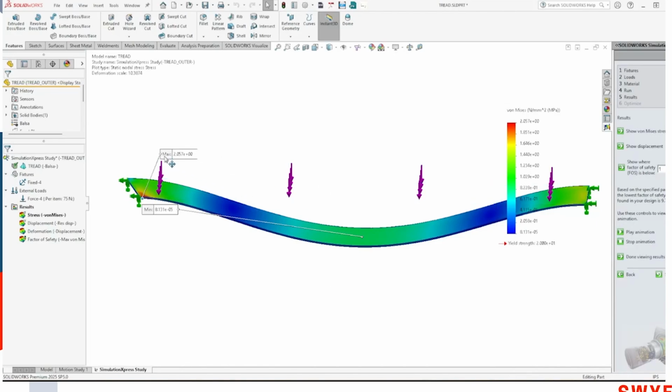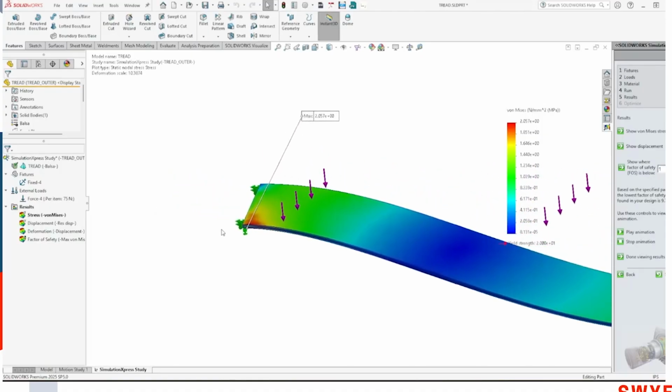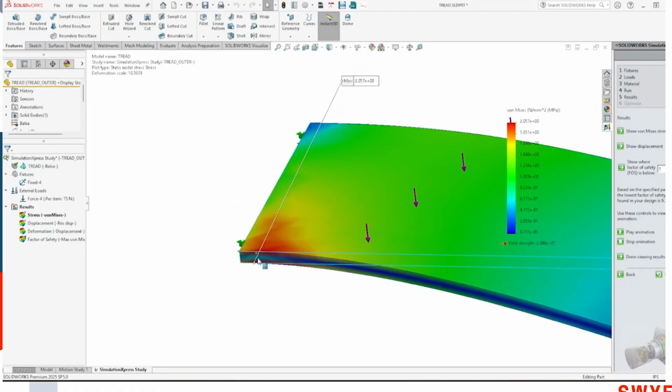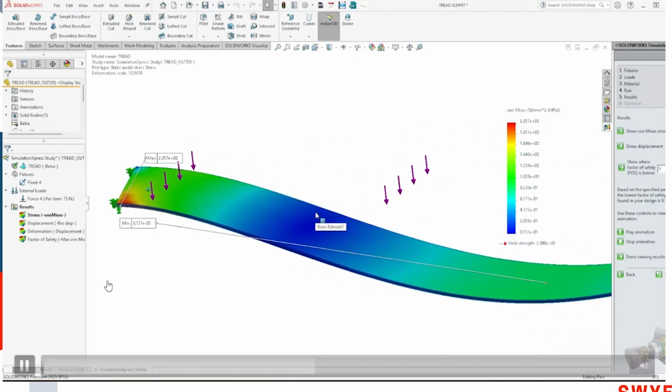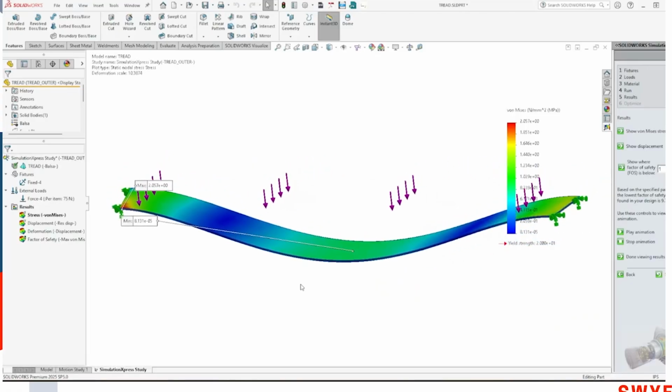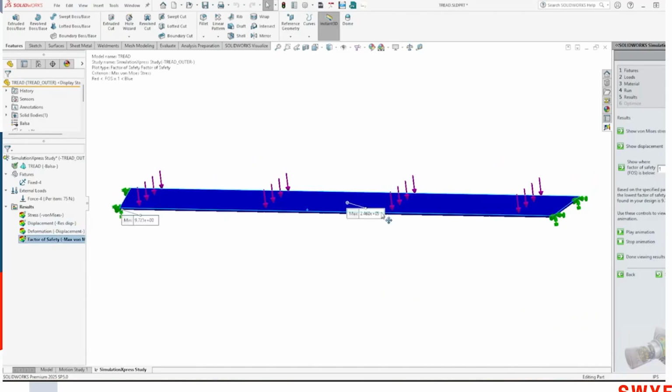Now keep in mind, the deformation scale up here is 10. So that's moving 10 times further than what you would actually expect to see in real life. But we get a nice stress strain plot out of this. And what this is showing, and I want to caution this, we're not teaching FEA interpretation, but what this is showing is where concentration or where deformation is high, not that red equals bad.